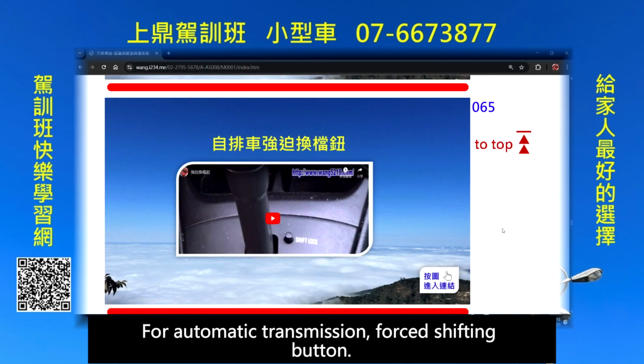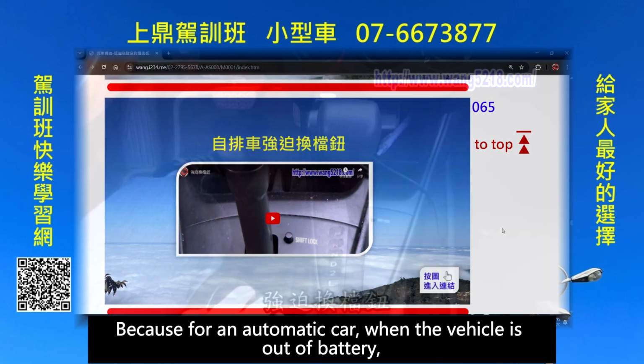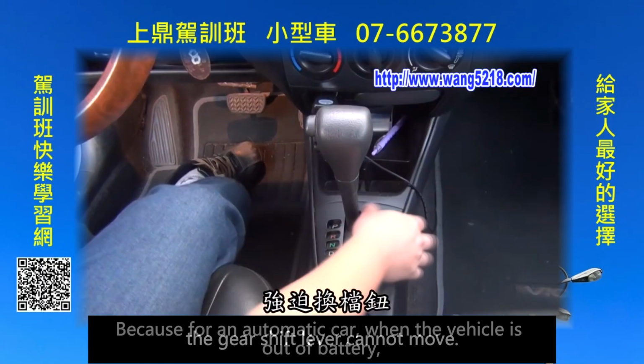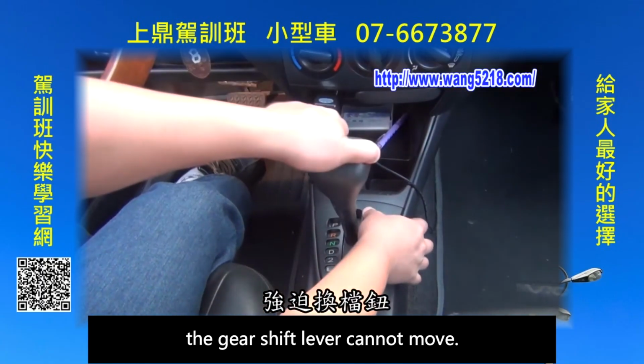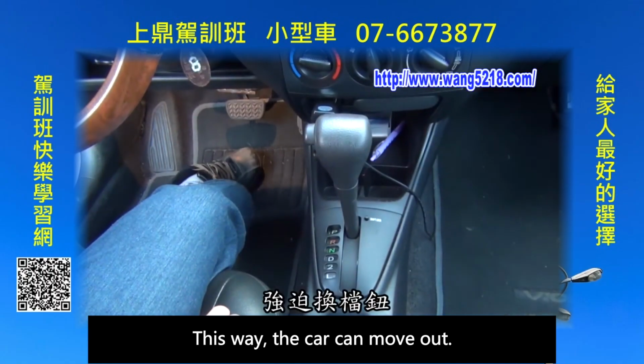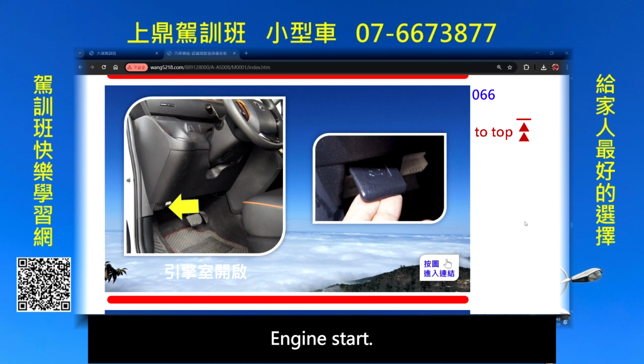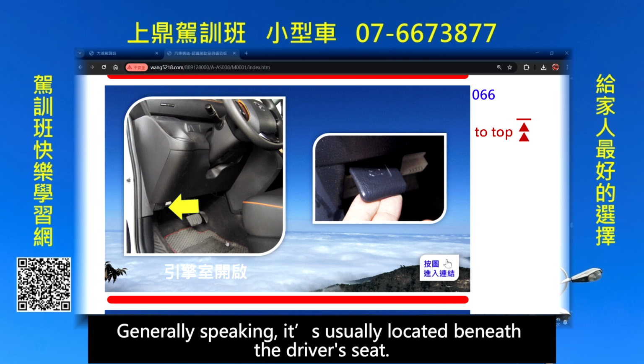For automatic transmission, forced shifting button. Why does an automatic car need forced gear shifting? Because for an automatic car, when the vehicle is out of battery, the gear shift lever cannot move. So forced shifting is necessary. This way the car can move out. So it has this design. Engine start. Generally speaking, it's usually located beneath the driver's seat.